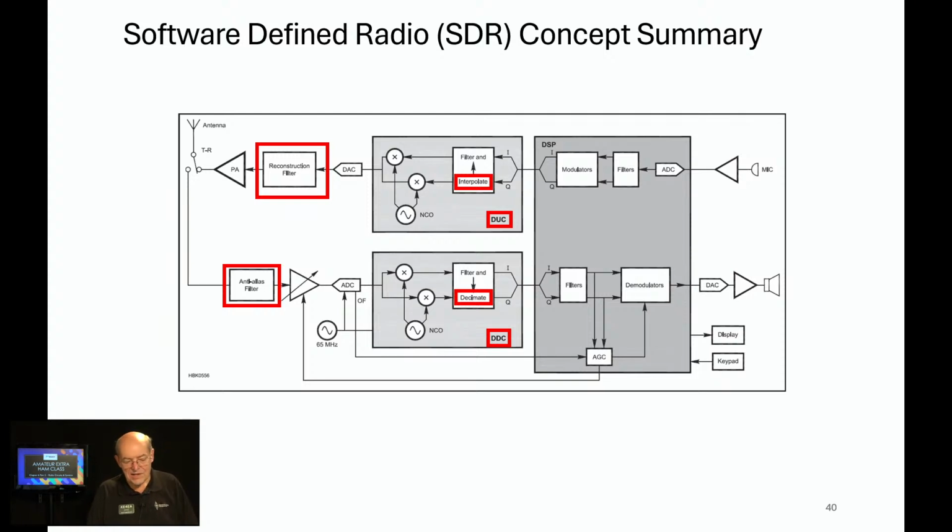All right, I'll give you some reasons. Almost any kind of signal can be processed: modulated, demodulated, filters, frequency synthesis. Functionality may be altered in software, with new features or improvements. It achieves the magic of DSP we just discussed. And a really big one, which I think has influenced the manufacturers to go this way, is that the parts count is lower. You don't have coils and capacitors, and you have many, many fewer parts. So lower parts count and cheaper. Of course, you'd think that would be reflected in the price of the radio, but not yet. I think we're paying for the technology that's inside.